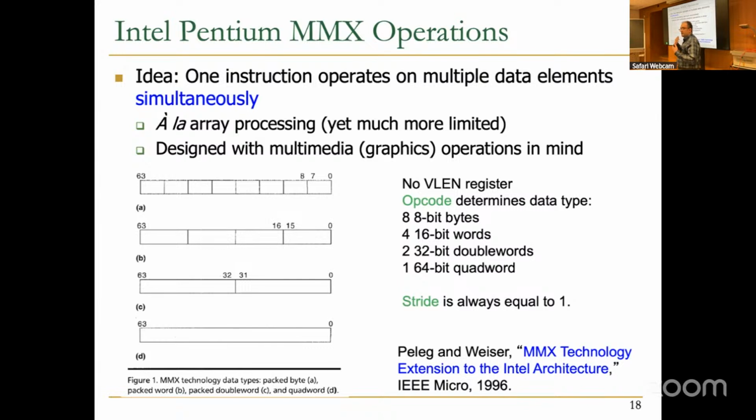In other words, you can say that now I have a vector register that has only 2 elements. You can even go further. You can chunk it to 4, or you can chunk it to 8. And having 8-bit chunks is actually quite good when you're doing image processing, for example, because pixels are usually 8 bits, and then you can use it nicely in order to do graphics operations.